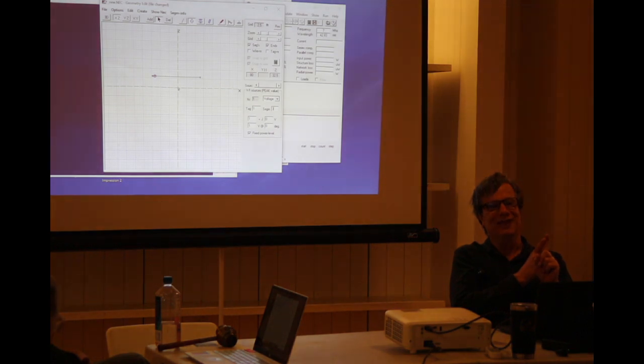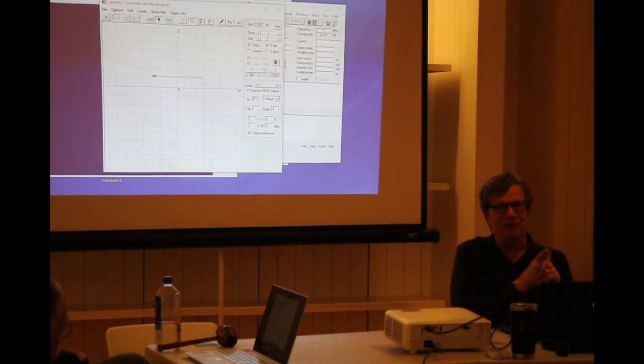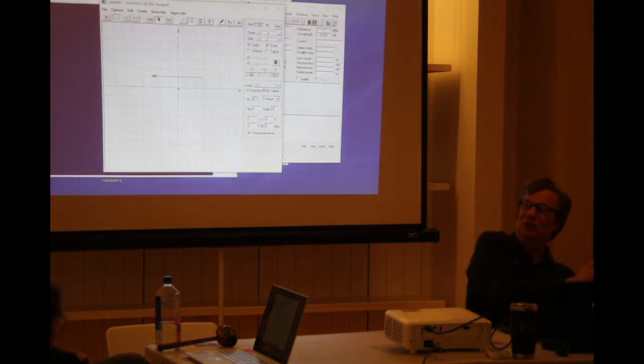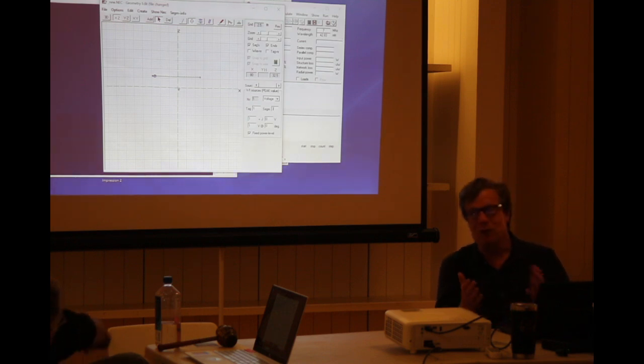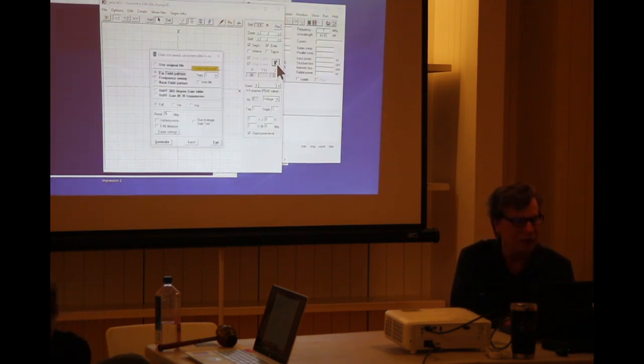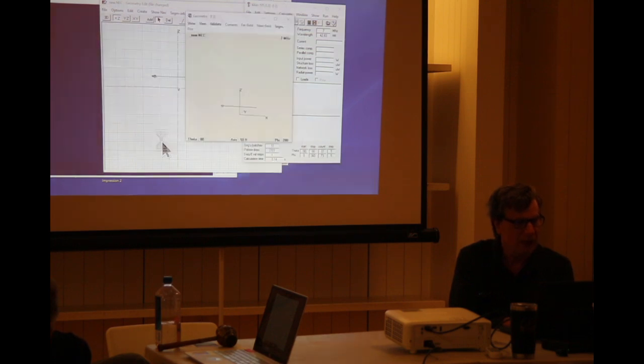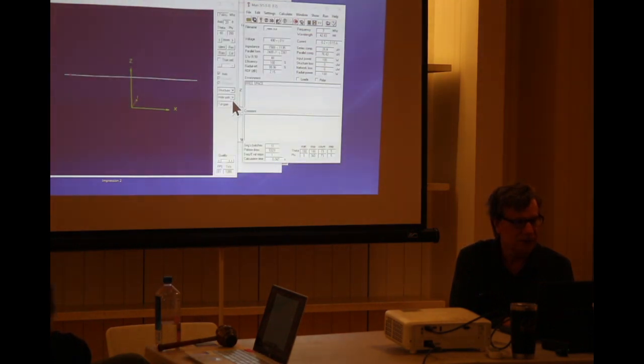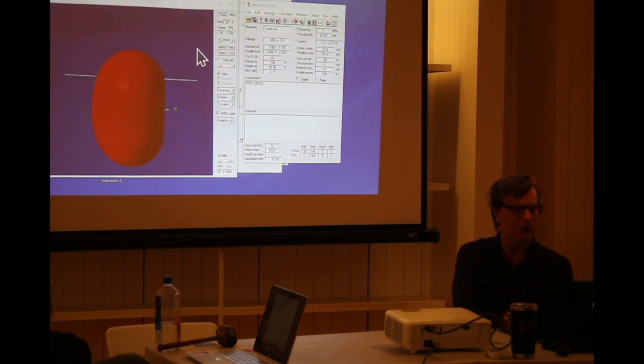Infinite. You're going to have infinite impedance off the end because there's no place for that current to go through. So we could put the feed very close to the end, but not there. So we'll do the far field pattern here. And just like where we feed the thing has absolutely nothing to do with the pattern, okay?